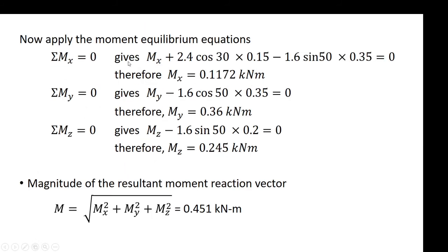That is why the moments Mx, My, and Mz are positive, and the other moments, depending upon the direction of the applied forces, can be positive or negative. So you can find out the net magnitude of the moment, as well as, if you desire, you can find out the unit vector from the components, and you can express it as a vector.